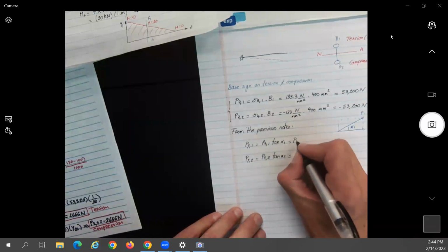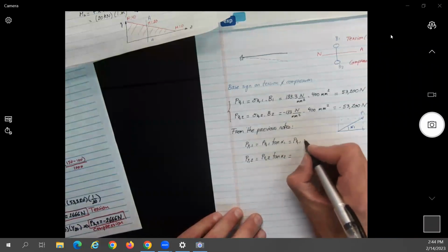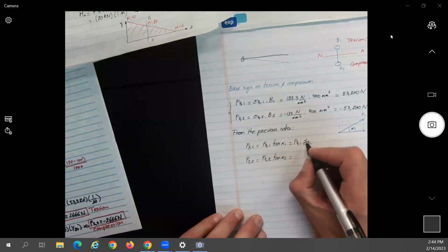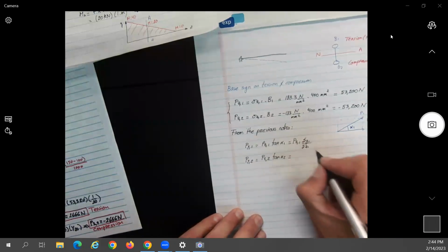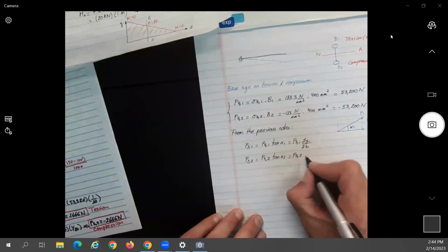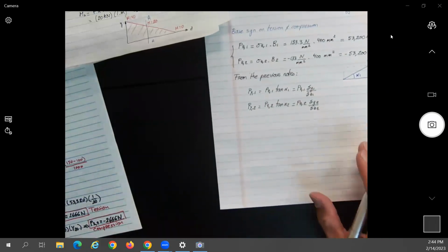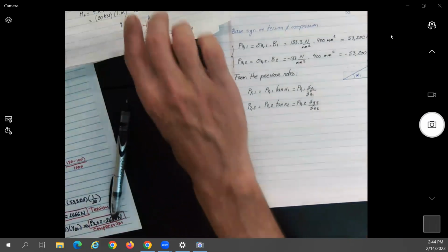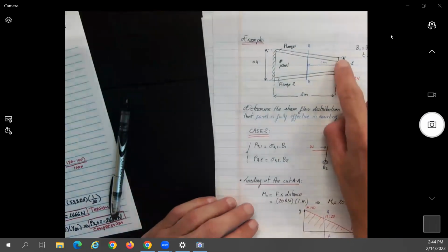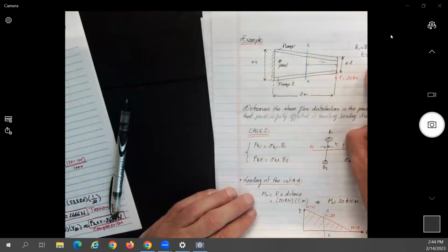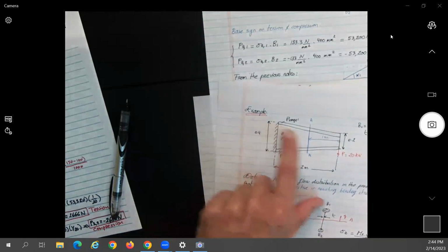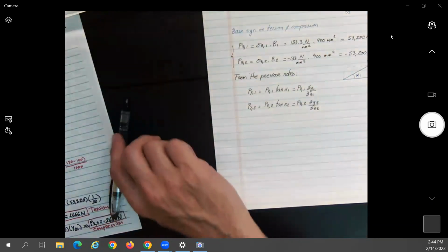Remember, I said you could write this as PZ1 change in Y sub 1 over delta Z1, and PZ2 delta Y2 over delta Z2. I'll do a figure now so that you understand. So basically, what are we looking at here? We are looking at what is the angle between the flange and the vertical, no? Okay, for each one of them. But instead of using angles, we can use the change of slope per unit length for each one of these flanges. Let me do a figure, so it's easier.